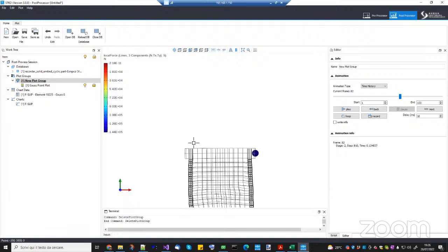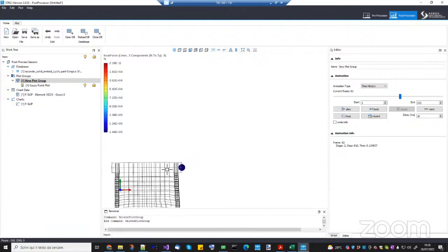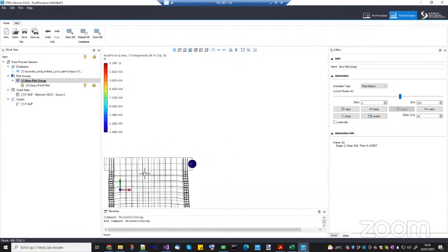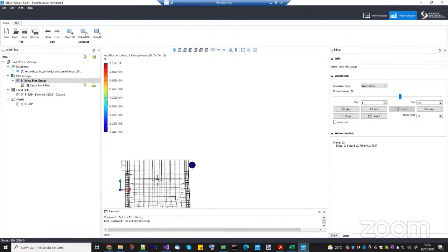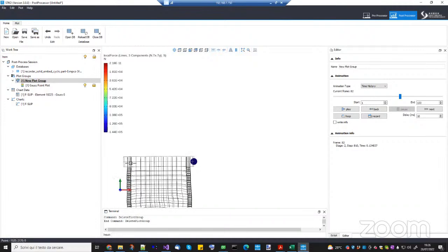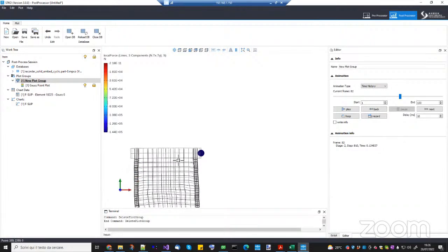Typically I would use this kind of approach when you really want to study the details of an experimental test. But of course, you cannot think of building an entire structural model with several shear walls entirely with solid elements. So it depends. It can also be useful to create this model to understand what physics are interesting or not, what is important to model or not. Okay.